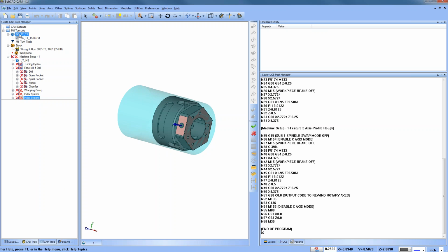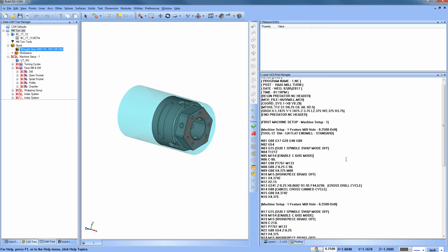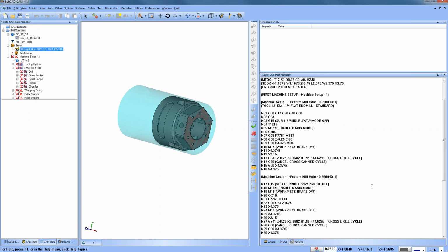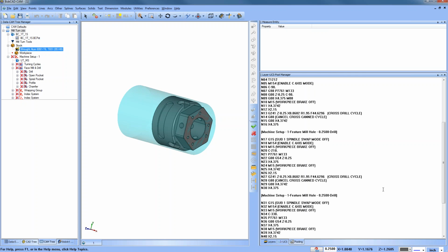Let's turn this one on, post it up, and then this is again a drill routine here where we index to those flats, and then we drill some of those holes, okay? So again, just some sample codes that you can look at. Now, again, there definitely can be different M codes that are called, and there can be different formatting. This is a generic Fanuc style, I believe, is what I'm demonstrating.